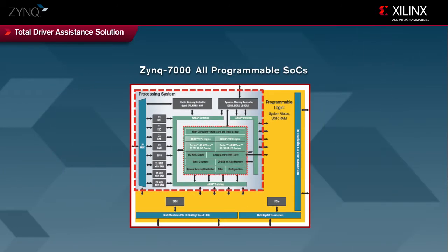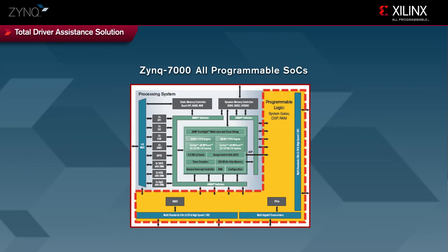Now, let's take a look at the Zynq-7000 all-programmable SoC. Zynq includes a complete ARM Cortex-A9 MPCore processor system in a dual-core configuration. This is tightly coupled with 7 series programmable logic on a single monolithic device. A family of devices with different logic densities, all with the same ARM processing system, allow for the optimum level of hardware resources and scalability for spanning low to high-end DA systems.